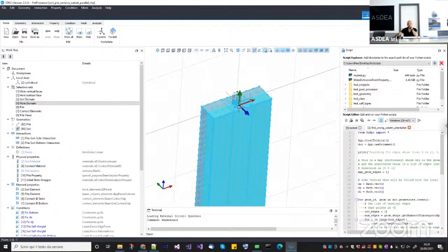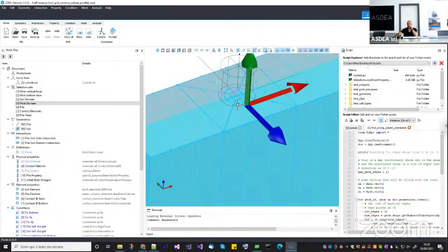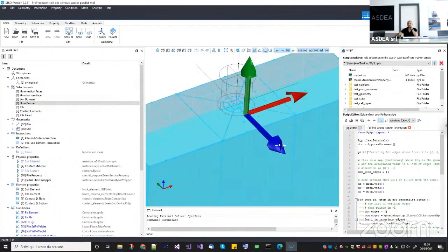Now, the only requirement for this contact element is to know what is the z-axis of the beam, because it already has access to the 2 nodes of the beam, okay? So it is able to define what is the x-axis. Now it needs a z-axis, not because the contact changes, because as you can see, the contact is isotropic, so it's the same.